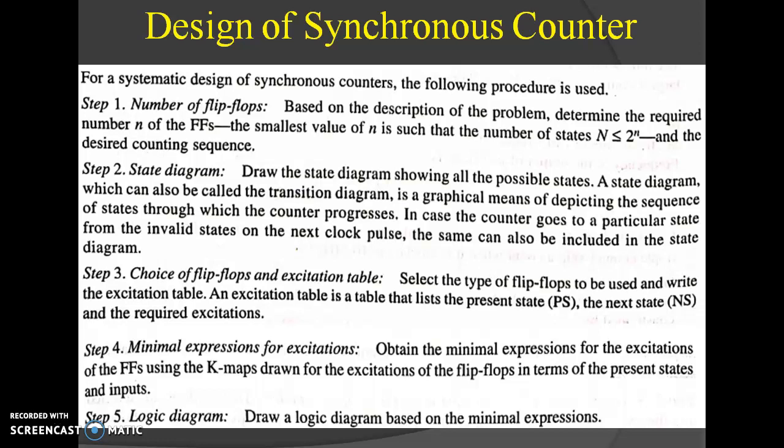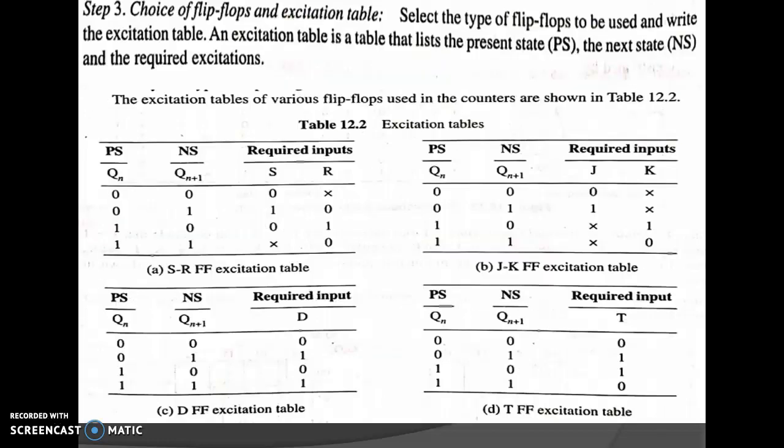Step 4. Minimal expression for excitation. From the excitation table, we will create the equation with the help of K-map. Step 5. Logic diagram. Draw a logic diagram based on the minimal expression.